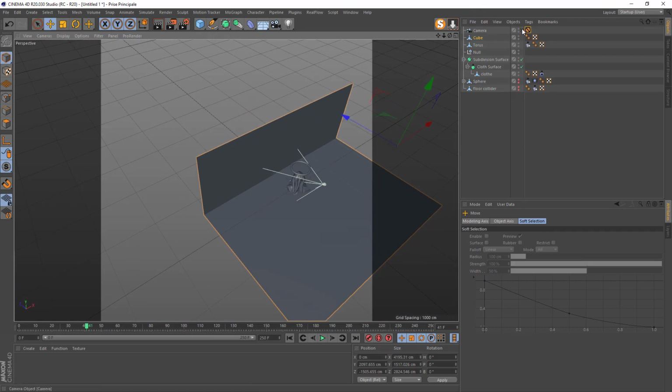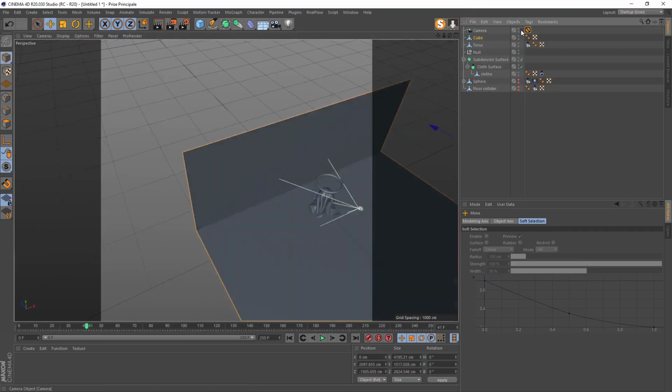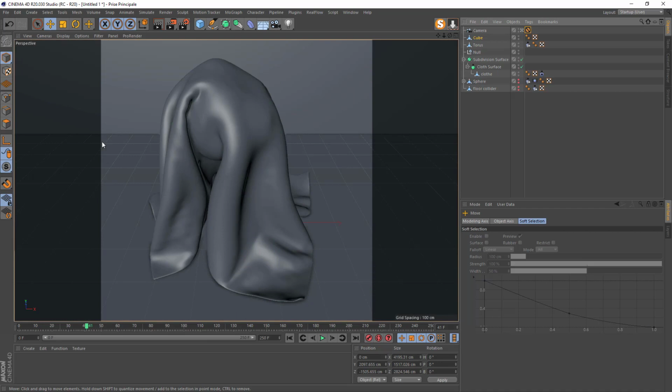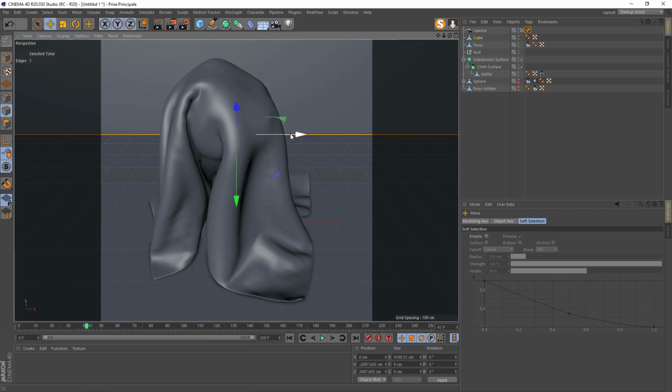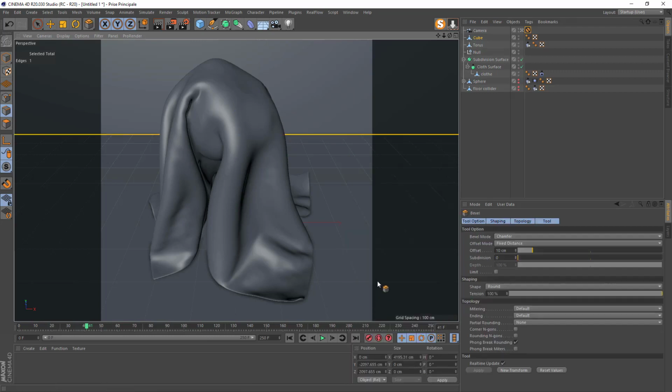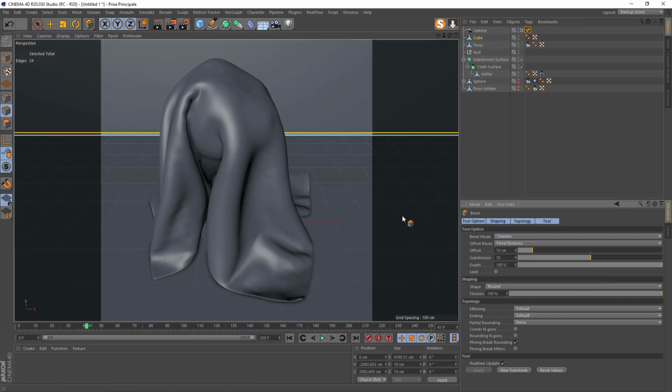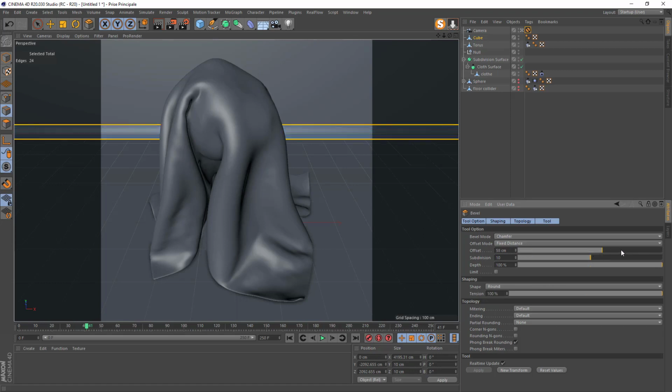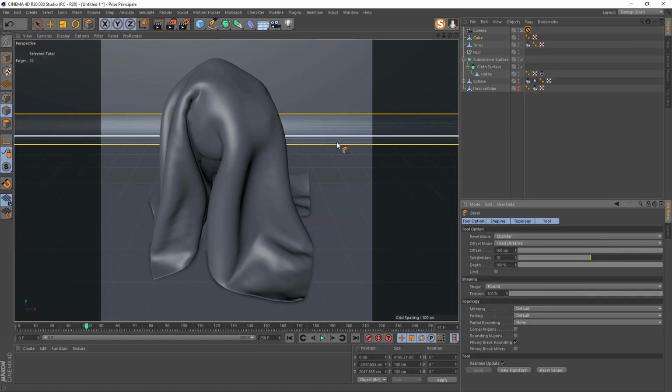You see, right click and choose Bevel. Bevel here. Put 10 subdivision and offset. You can, you see, increase. It makes this corner round, so at the render it's quite better. But 100 is not enough, so I will put 200 maybe.